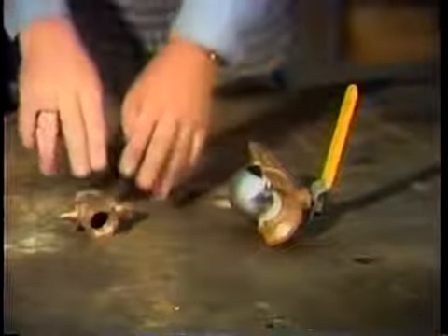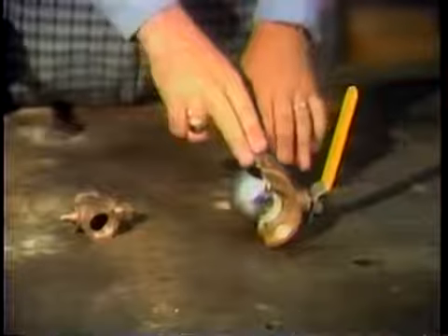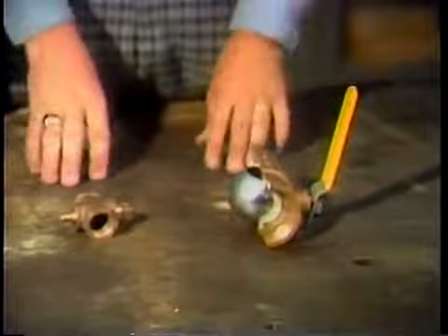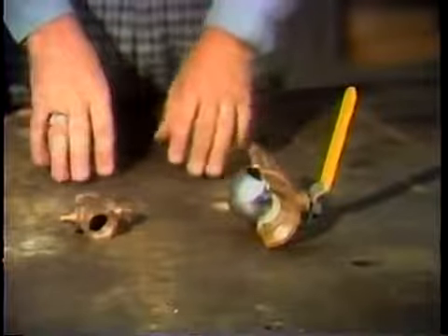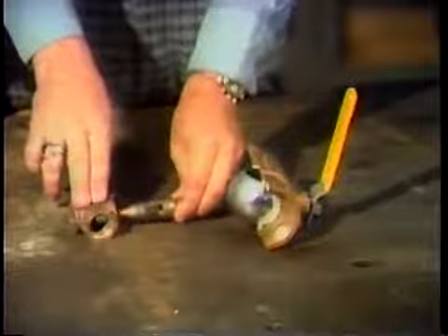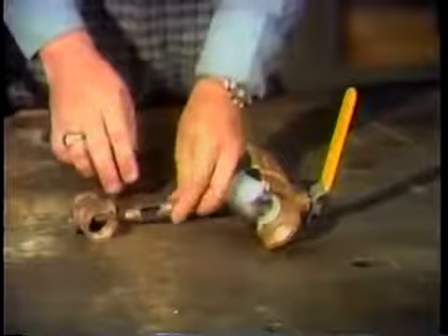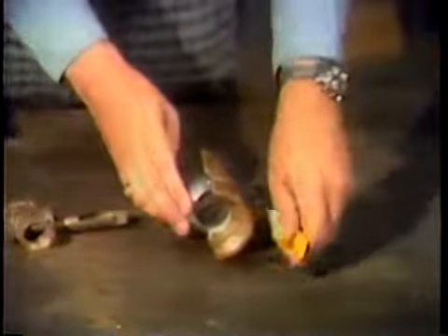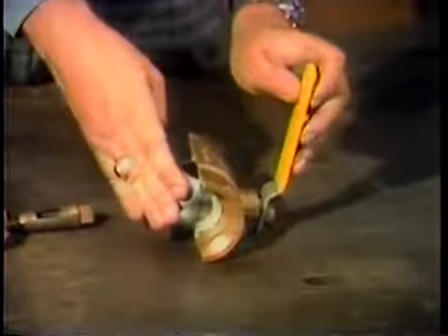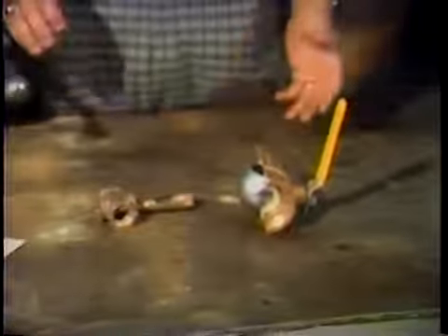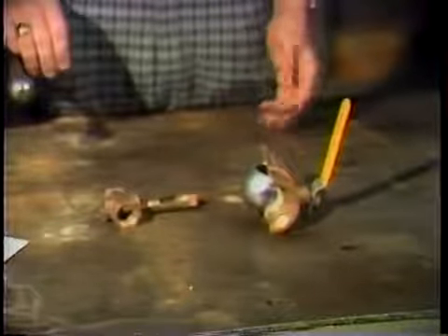Now we're going to look at two valves that are very much alike, a plug valve and a ball valve. In contrast to most other types of valve, they do not have discs which raise and lower. The plugs on these valves, or the ball in this case, open by rotation. And when the valve is actuated, the ball makes a quarter turn, starting and stopping the flow very quickly. Usually this design does not provide the same tight sealing quality of the globe valve, but these valves aren't generally used in systems requiring a tight shutoff.